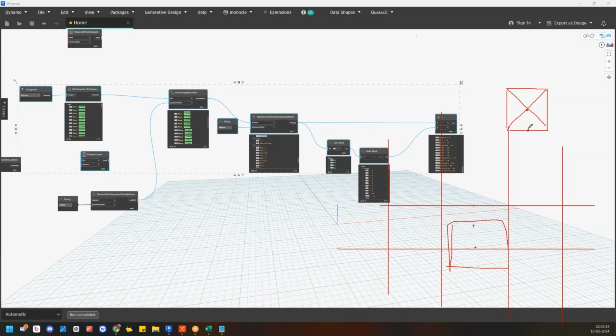In such cases, you have to add the diffuser difference. If it is a 150 by 150, let's add 75. First you will get all the points of the grids, the center of the grids, and then you will add 75 to it. Simple. For example, let me show you.